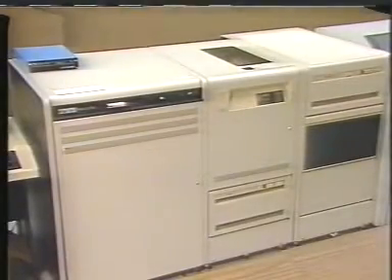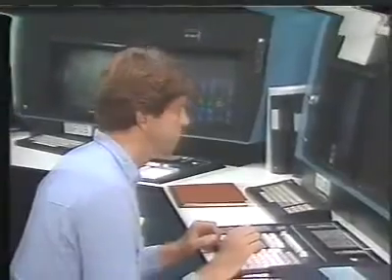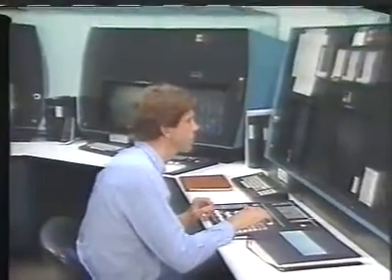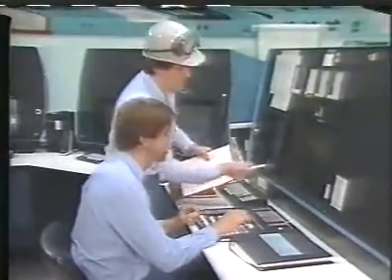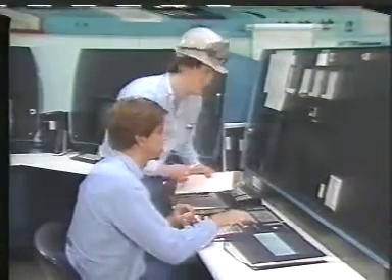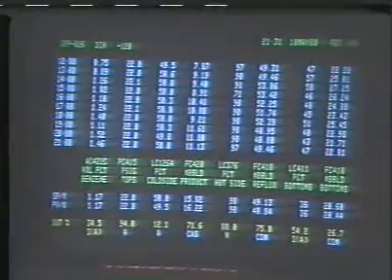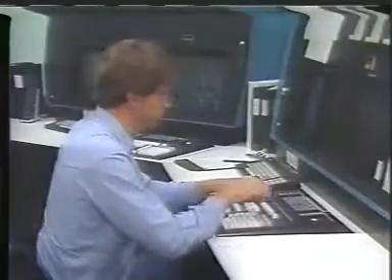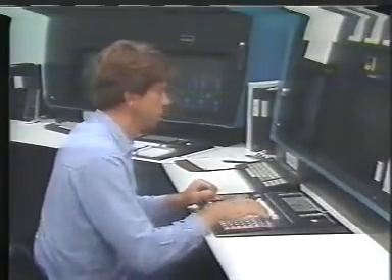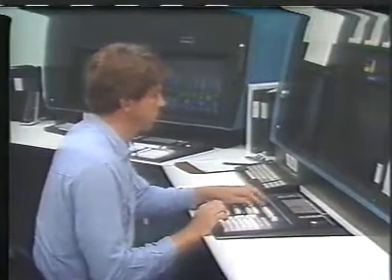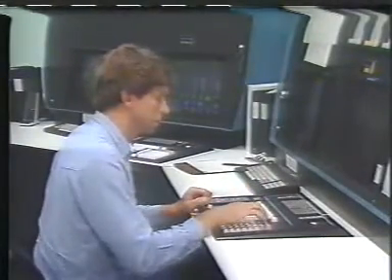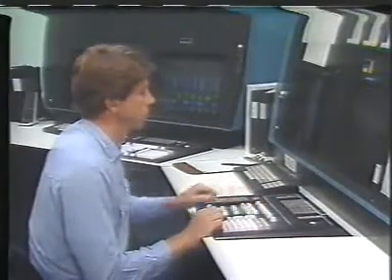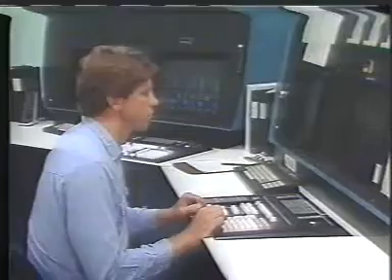The majority of the computer systems on the market are equipped with alarm displays. These displays automatically flash to warn an operator about any abnormal operating situation. Other displays that can be shown on CRT consoles include checklists, flowcharts, and full-color schematics of process equipment. Any of these displays can be called up instantly with a touch of the finger. This quick and orderly display of information makes it easier for an operator to understand the dynamics of the process and gives him more time to devote to controlling the operation.